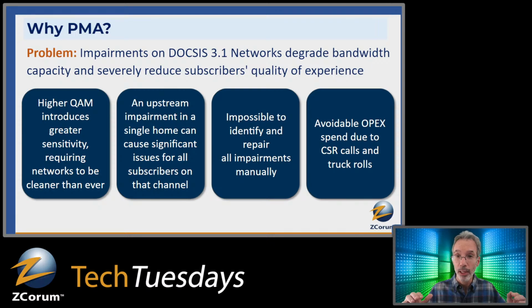You can have lots of your customers up at a higher modulation level and just exclude certain areas where there's noise. And you can have certain customers that, maybe because of their conditions, can only get 256K QAM, but you want most of your customers to be able to get the highest order, 4096 QAM. But with that sensitivity, if you're not managing that properly, and again, it could be automated, then you're going to have all of your customers drop down to a lower modulation level, and you're not getting out of the investment what you really should be getting.